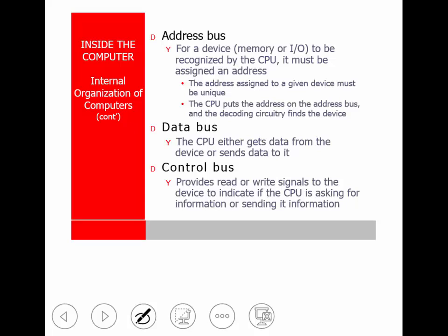the address bus. The microprocessor we're going to be using for the lab is a 16-bit microprocessor, but when I go through and talk about the 8086, it's got a 20-bit address bus. Now, the size of the address bus will determine how much memory a particular microprocessor can address. If you look at an 8086 and 8088, it's got 20 address lines. So if you take 2 to the 20th, that particular microprocessor can address about 1 million memory locations, 1 meg of memory.